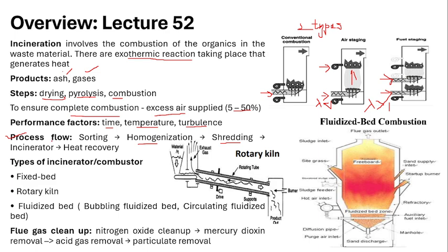Okay. Now comes the incinerator. In the incinerator, we are providing the air. Our fuel is our waste material. In the presence of air, burning of the waste material happens, and it is going to release a lot of energy. The temperature will typically be more than 900 degrees Celsius, at minimum above 500 degrees Celsius. It can reach about 900 or above 1000 degrees Celsius while it is burning. So much heat energy is released while burning the waste materials.